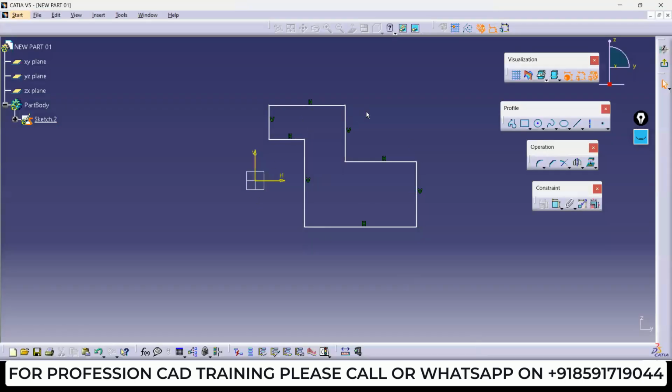So first, you can see this color is white. There are three types of constraint types. One is under constraint, second is fully constraint, and third is over constraint. In the first condition, we have not provided any dimension to this entity, which means it is under constraint. It means we need to provide the dimension.